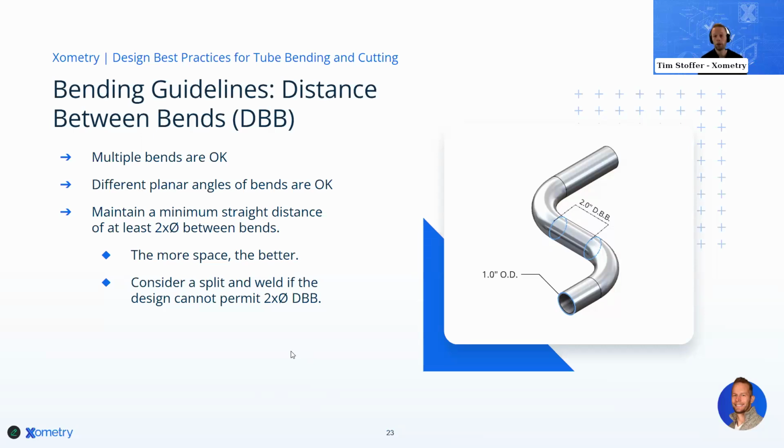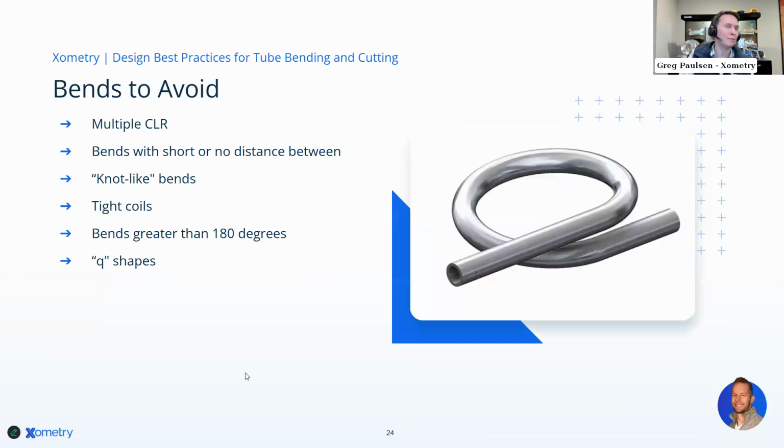Otherwise, you might want to consider putting a weld in there, or we would consider putting a weld note on your quote to say, hey, we can make this part for you, but it might have a circumferential weld in between those bends. And by the way, on that note, we do read drawings, and if there's welds or something like that, we can incorporate that in. If you have requirements, if you're a welder yourself, then you want to leave ends long on the design that you're getting, just ask. We'll incorporate. It actually is nicer because it may save you a business day or so for leaving ends long. And what that means is leaving extra space for you to grind down and fit up just as you need it there.